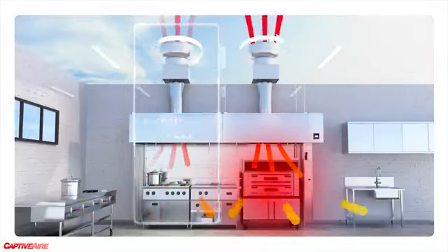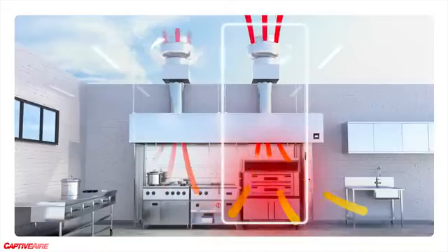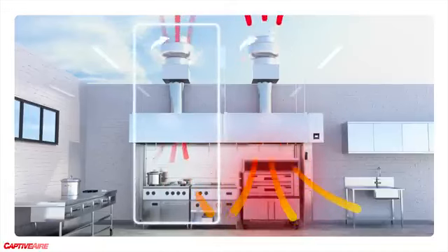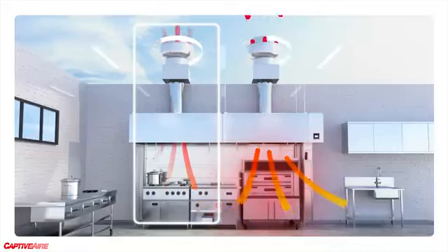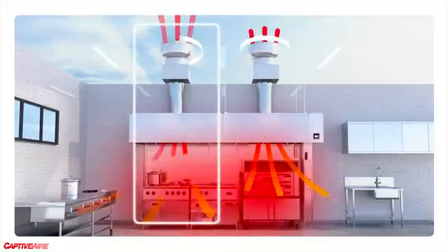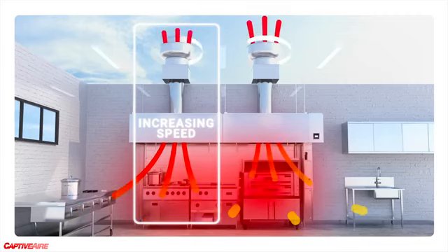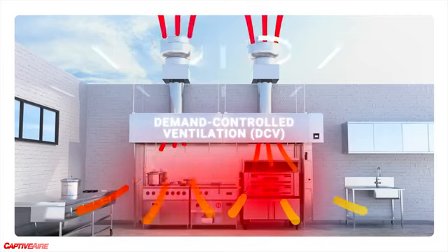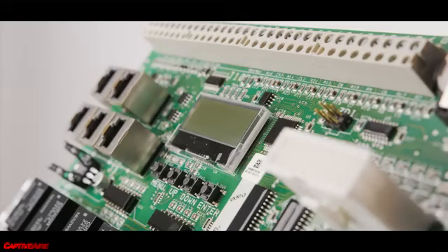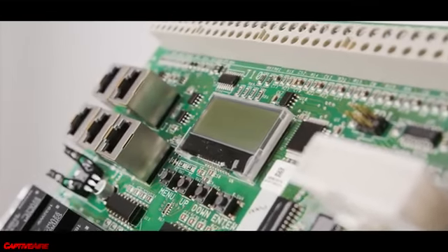So if it's super hot over here, we can have this fan going full speed, this fan maybe low speed just to help make up for some of it if it's drifting. And then temperature kicks up over here later, then we spin this one faster. So it's all individual control per what's needed where. That's just one example of the many things this board can handle.